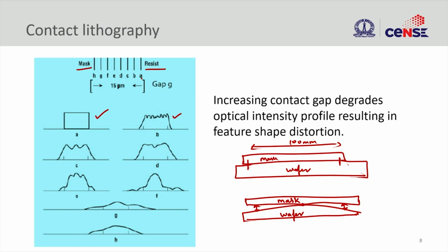You see this small diffraction happening and all these fringes that we discussed earlier on in projection proximity printing. That comes into effect, and then this effect worsens, it keeps on becoming worse. Like I mentioned, you are going to increase your critical dimension because you're going to have this penumbra effect, and then your intensity is also going to go down.